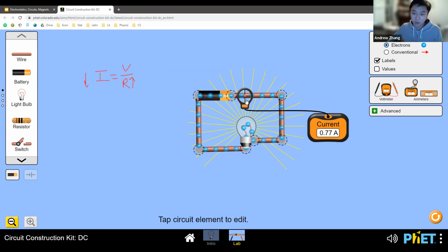Therefore, any scenario where there's a buildup of charges, where the current isn't the same at all places, will be corrected to become the same at all places, because that buildup itself will decrease the amount of current going into the place while increasing the current going out, which will mean that eventually current will correct itself, and everything will be back to how it should be.